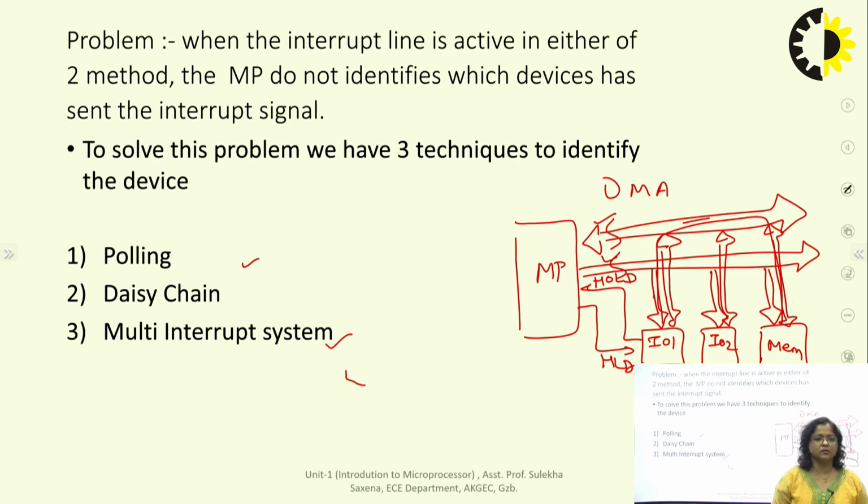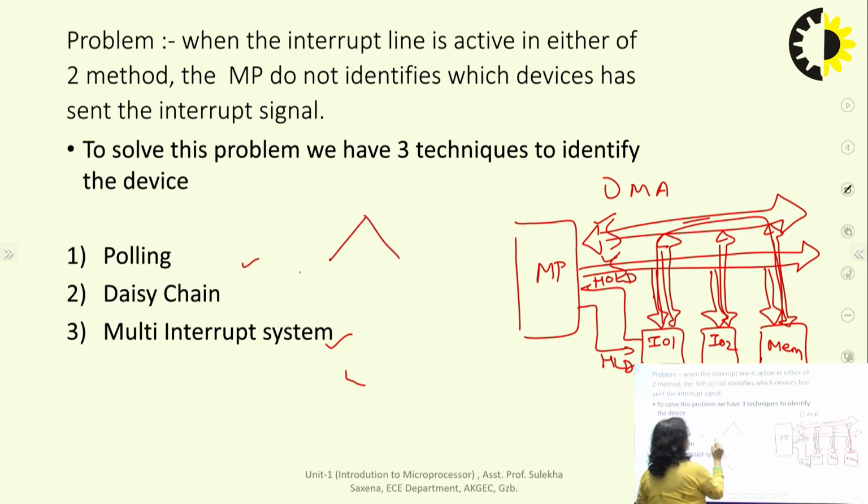So, in this lecture we have discussed various addressing modes of 8085. 8085 consists of 5 addressing modes. We have studied the various addressing modes in detail with an example of each, and then we have discussed the various data transfer schemes that occur in the 8085 microprocessor. We can say that the overall data transfer scheme is divided into two types, that is serial and parallel. Normally 8085 executes data transfer in parallel mode. Only if requested does it go for serial data transmission, transferring the data serially through the D7 pin.